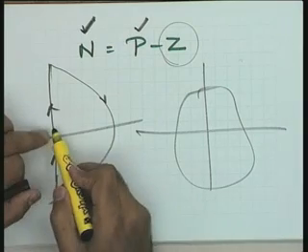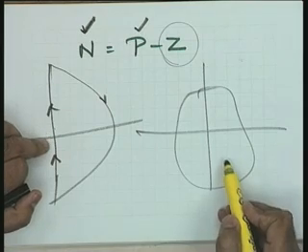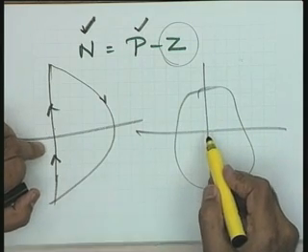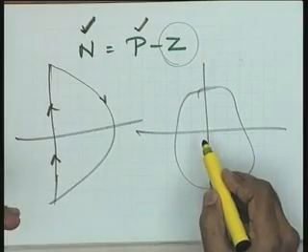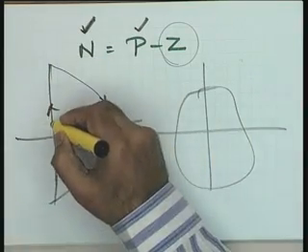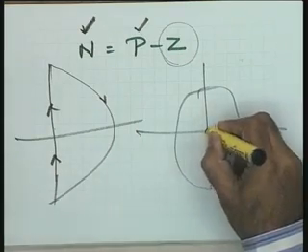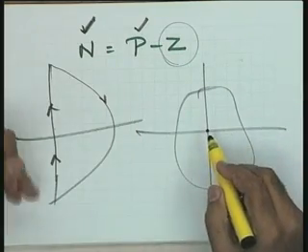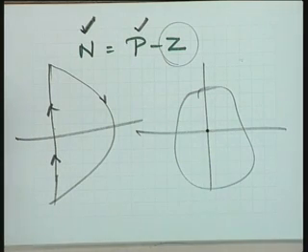If there is a 0 on the contour, what will be its mapping? The contour will pass through the origin. The contour in that particular case will pass through the origin, and this actually is the case of marginal stability. So, this case also will come up. That is actually if this contour passes through the origin, this case corresponds to, as you have seen in this particular case, the zeros of the system, zeros of, sorry.